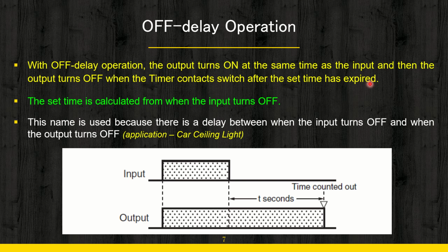Now the particular operation that we are talking about is the off delay operation. Off delay means that after the input signal is taken off, that means when the input is turned off, then your output will be turned off after a certain delay. You can see here, this is the input. You have stopped the input or turned off the input.